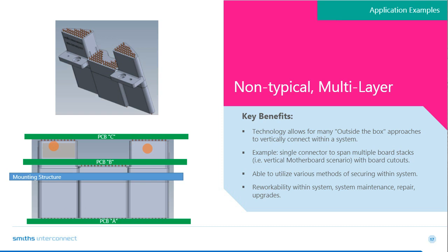You accomplish this, but it does require a hole in the board that matches the geometry or feature of the connector. Again, you'll notice it allows you to incorporate that solderless interface to provide the degrees of freedom in the alignment, the X, Y, and Z directions, and the ability to easily dismantle the assembly if needed for rework, test, or repair. Lastly, we are providing a specialized mounting method that allows for tolerance absorption between all three representative PCBs by keeping the interposer independently mounted from the PCBs.